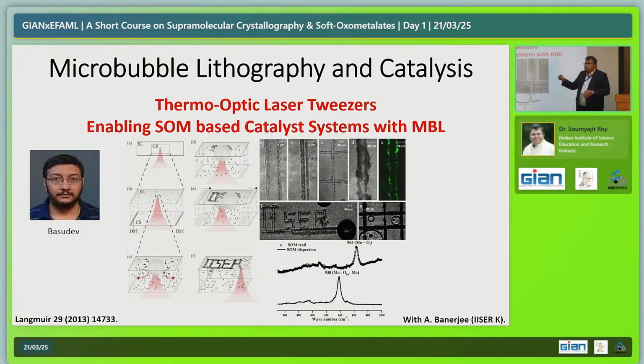That happens with the speed of translation of your laser tweezer. So if you translate them very fast, then the bubbles do not have time to grow that much in size. You pull them very fast, you get thin patterns like this one. But if the residence time of the bubble with the laser, the contact time or the residence time, whatever you call it, is higher, then they have more time for residence. Then you get thicker